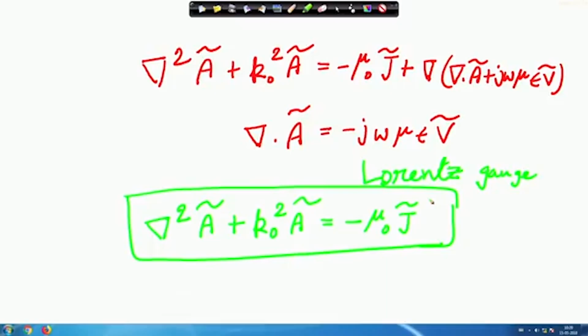If you look at the electric field, we cannot say that okay, j is in this direction, so electric field will also be in this direction. Now, that is the beauty, that is why we have a difficult problem of finding E and H, that we have put a less difficult problem, that let us find j.